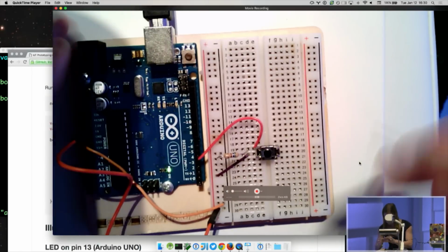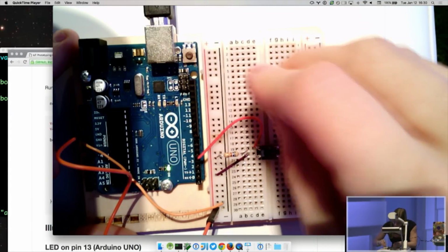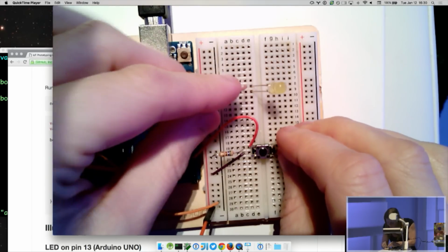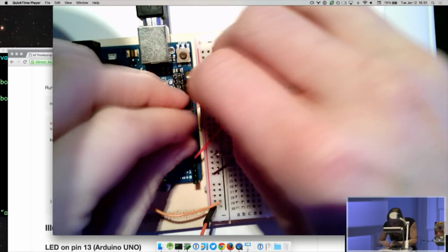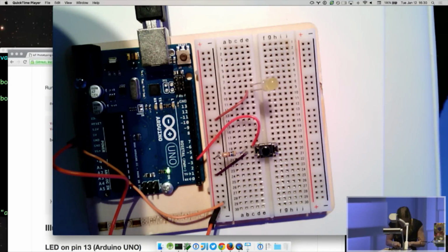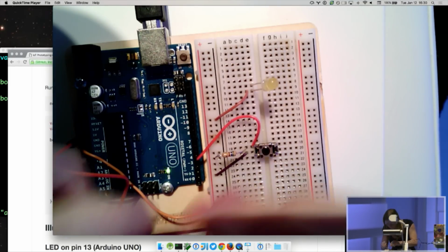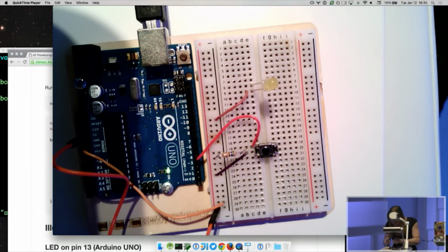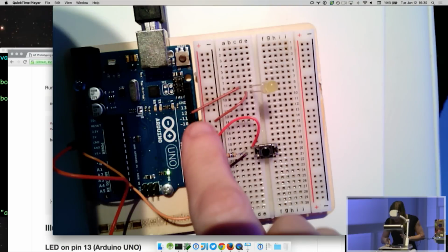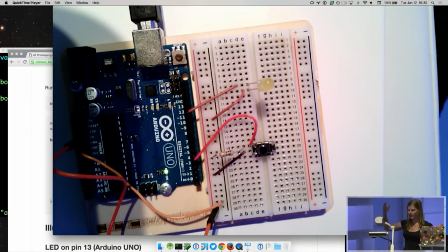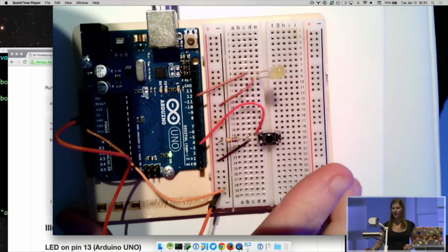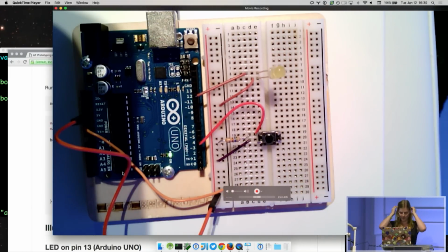So what I'm doing is I'm remembering which pin is long, because that's the one that has to go to the high voltage. Then I'm going to take the reference low from that little rail, and connect it with the jumper wire. And then I'm going to use one of the digital outputs from the Arduino to make the LED light up or dim. So I'll grab a brown wire again. Should bring more colors. And we'll use pin 12. So now if pin 12 is set to high state, to 1, we're going to have a 1 on one side, and we have a 0 that's already there, and the LED will turn on. If it is not, the LED will stay off, because there'll be 0 on both sides, and no charge will move, and no LED will turn on.